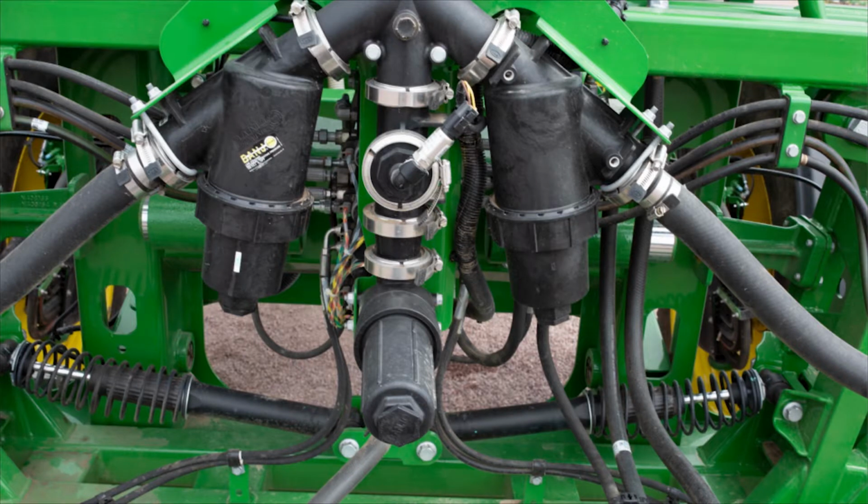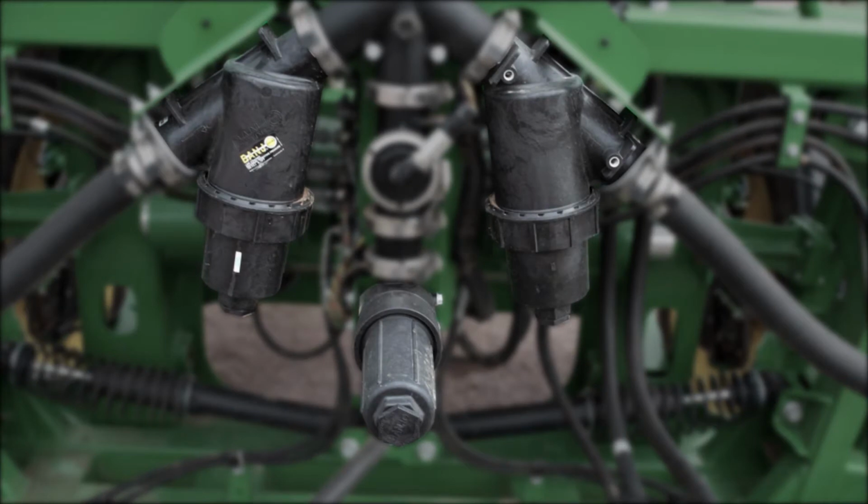When we look at the back of the machine, one nice feature that changed when John Deere updated their 4 Series machines is we've located all of the boom strainers in one location. So we've got the left, right, and center boom strainers all in one location. It allows for basically easy clean out of any of our boom strainers if we have any contaminants. One thing to note, there was a running change in the Deere machines for that center strainer. Older models did shrink that down to a 1-inch line. The newer ones are 1.5 inches. That was a change that was made in 2017. So something just to be aware of.